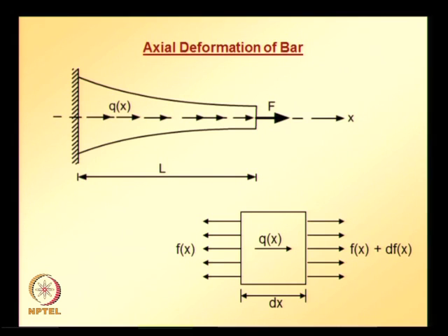So, the governing differential equation explaining the physical phenomena here, that is axial deformation of bar, can be derived by considering equilibrium of forces acting on an infinitesimal bar segment as shown in the second figure.